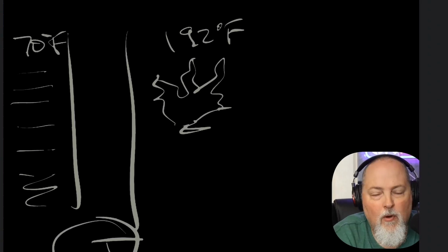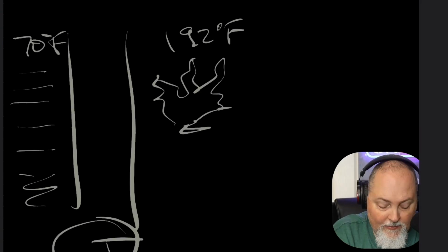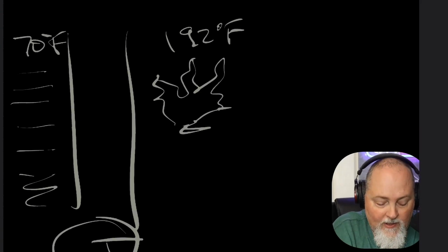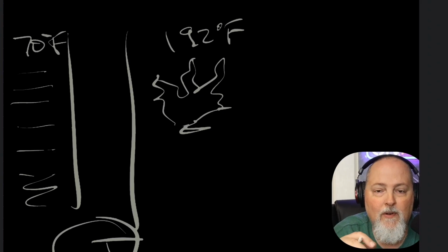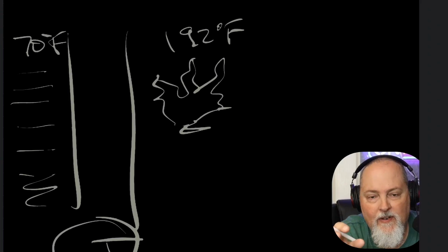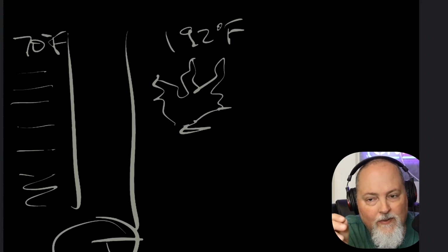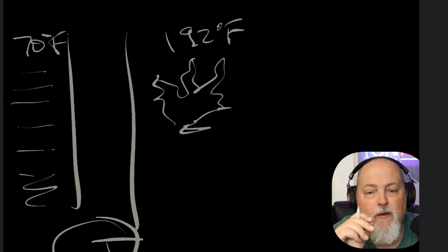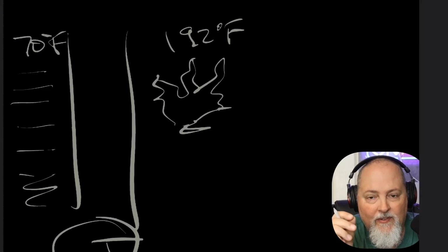You also have to understand the coefficient of thermal expansion for that material. And so you have to understand what that coefficient is, what that resistance to temperature transfer is. You also have to understand the modulus of elasticity. So modulus of elasticity means stiffness. A material with a higher modulus resists stretching or compression more than a material with a low modulus of elasticity. So when you hear modulus of elasticity, think stiffness.